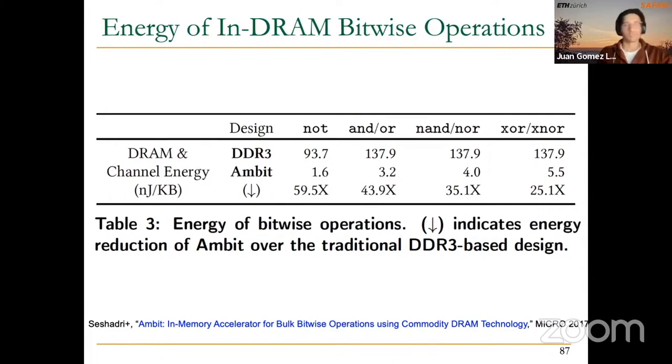And when you do the OR operation with the majority operation, isn't it dangerous that you get an undefined state because you're in the middle of the logic level? That could potentially happen. The fact that we are using 3 operands and these 2 operands can only have 2 different values, 0 or 1, makes the bit line finally go either to 0 or 1, depending on what's the majority of charge, either 0 or 1.